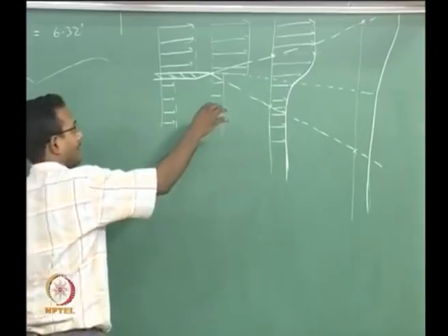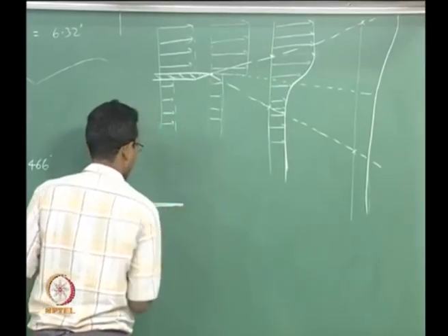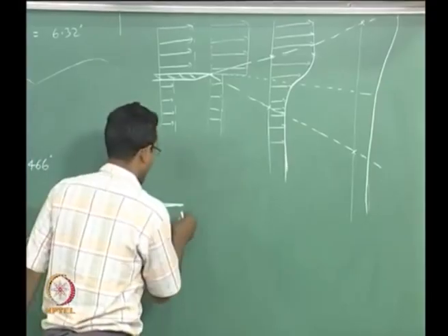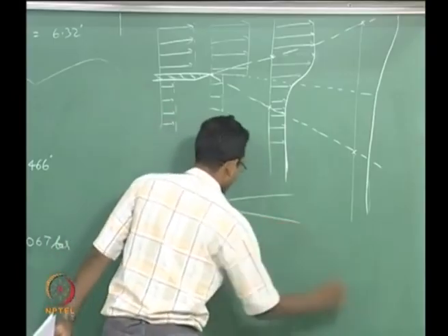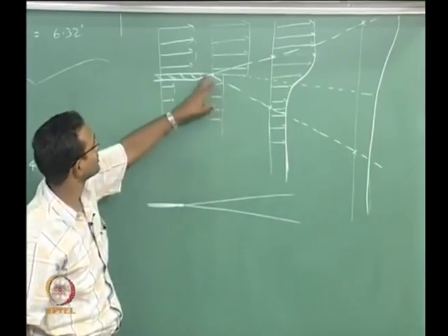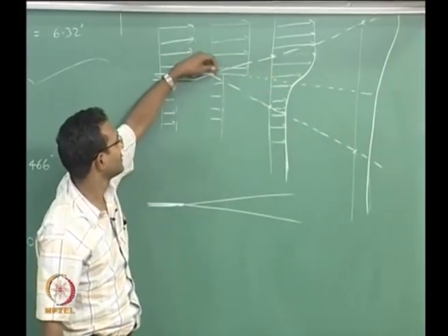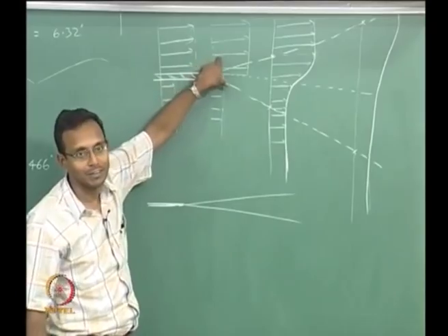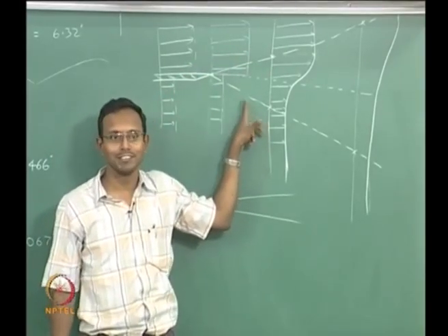Now, I will go for a different picture. I will draw a very thin splitter plate, and I am going to draw a more realistic shear layer growth that looks more like this. It will not be typically that. Oh, I wanted to talk about this going down dotted line. Typically, when the pressures are the same, the velocities are different, the P naughts for the top and bottom are different values. Which one is higher?